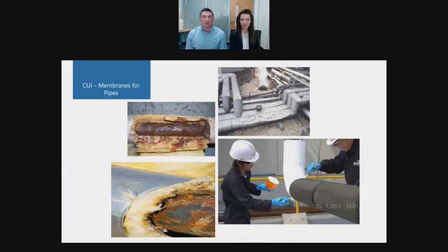This is to prevent corrosion under insulation, or CUI. As you can see from the picture, CUI is often unforeseen and it can potentially cause equipment failure. So it is essential that pipework and vessels are inspected regularly for this. Traditional metal cladding materials have inherent weaknesses at joints. These can be damaged by mishandling and impact. For example, workers walking across pipes damaging the protective cladding, as you can see in the top picture. As a result, this causes further gaps between the joints, increasing the risk of water penetration.